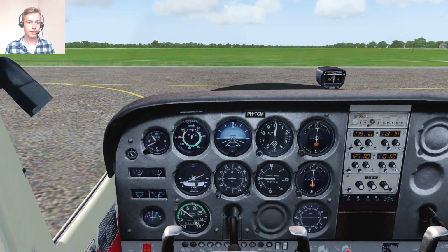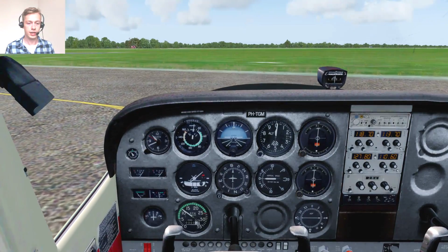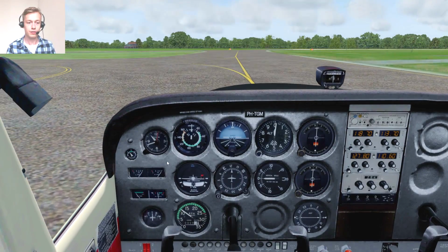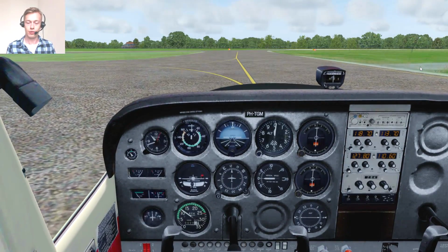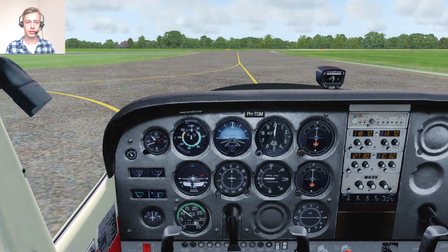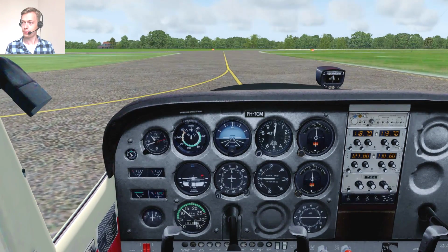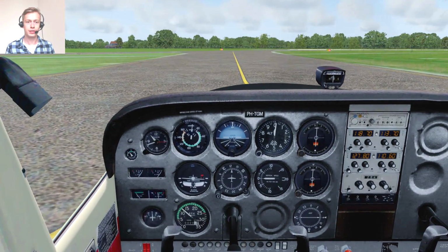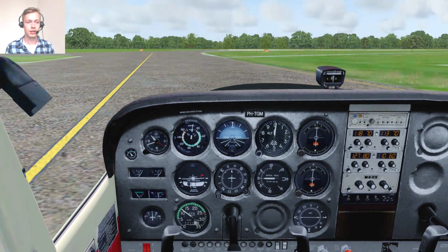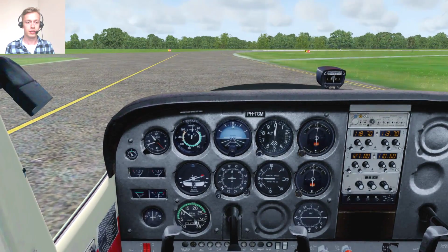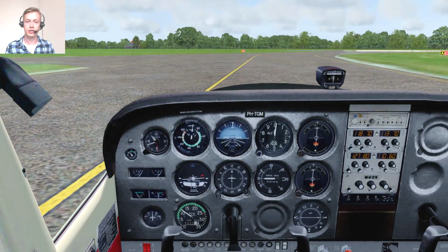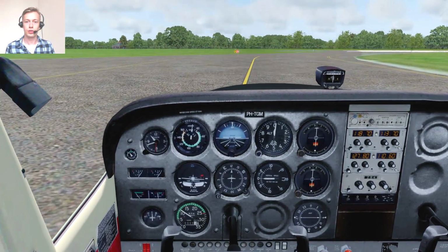I'm gonna turn left here. Just take it easy, don't taxi too fast. It's really not necessary. Now I've loaded up the aircraft with plenty of fuel, as you can see, so we're nice and heavy. So we have all the time available in order to practice VFR. And as you can see, holding point Sierra 1 is coming up. And just some info, sometimes they might ask you to go to one particular side of the taxiway so that another aircraft may pass. You're a small airplane, so this can happen. So keep that in mind. As you can see, runway 23 is here, and we'll hold short at the holding point.